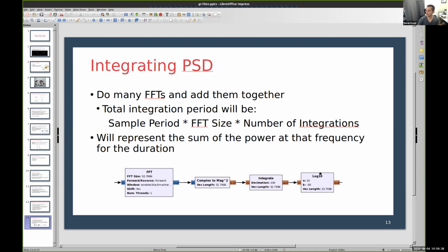And then we're doing a 10 log 10 operation here. The negative 30 is if you wanted to convert it into dB milliwatts, decibel milliwatts. But given the signal isn't calibrated, that's not really accurate. It'll just be a static change in the number. It won't affect the end plot in appearance-wise. And then we would view the data in the next step here.